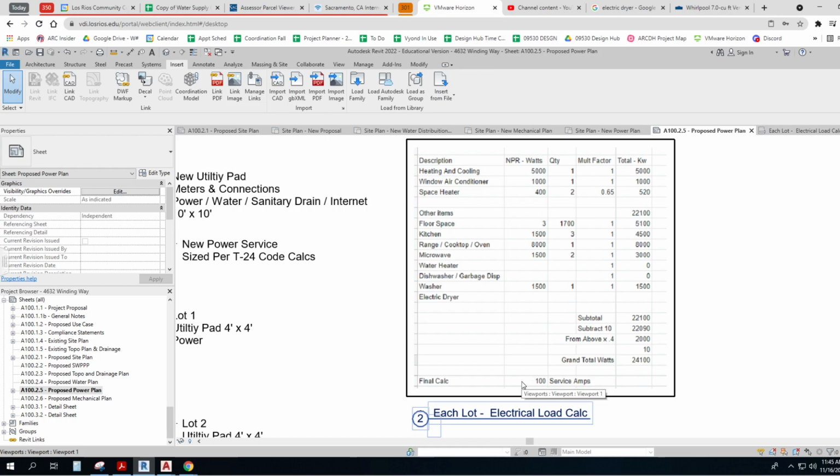Even though you wire up most of your house for 110, and even though most of your appliances and things actually work on 5-volt DC, those all are transformed down or wired to different legs. What comes into residential houses around here is 240 volts AC.